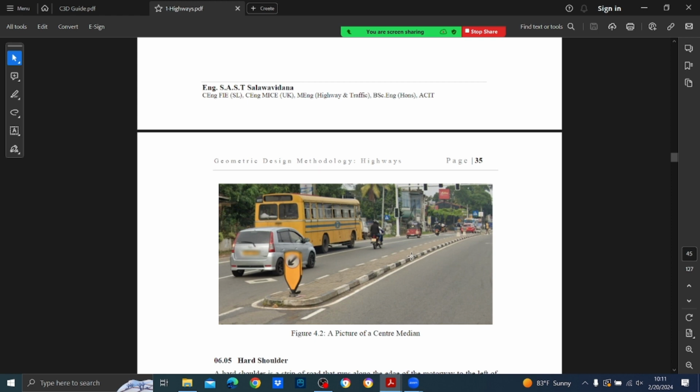That is for safety, right? Usually for all new four lane roads, we try to provide a center median. But the problem is, in the Colombo area, sometimes we have 4 lane roads without a center median. So they are not very nice, because there is contra flow, and there can be ill-disciplined drivers who try to encroach on the other side of the highway, and that is very dangerous.